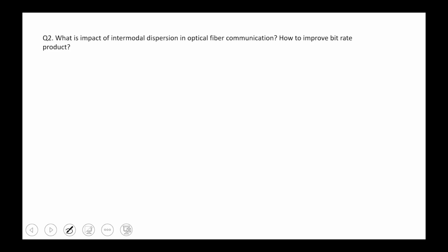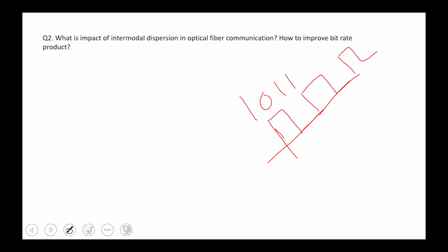Sir, just tell me one thing. As we transmit 1011, can you please note it down with me so that it is clear to everyone, how this is transmitted through optical fiber? It depends on the coding. If I use non return to zero, it is on-off. If I am using return to zero, then how will it propagate through the fiber? Like that, this signal will return to zero. This is zero, this is one, and then again one, and we continue that.